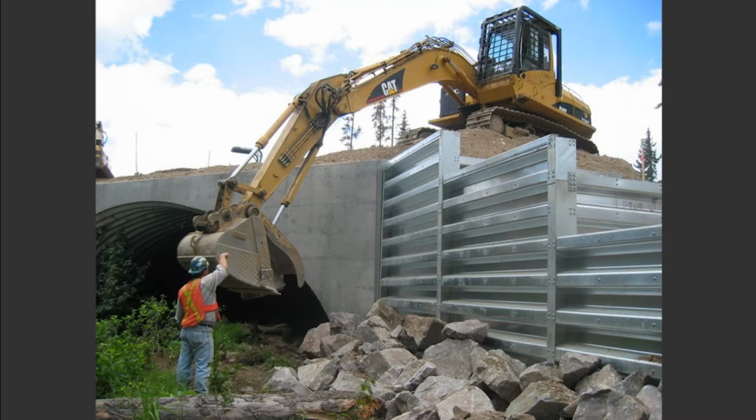Bin wall in general is a fairly robust retaining wall system capable of handling fairly high settlements, high loading conditions, and fairly harsh stream conditions as well. It can be installed in submerged conditions. The one thing to note there is that it's important to ensure that the backfill that's used won't actually be washed out of the bin. Typically in submerged conditions, we'll make sure that we're specifying material that's larger than 3 to 5 millimeters or so. If that's difficult to source, we can also line the interior of the bins with a non-woven geotextile just to prevent migration of the fines.